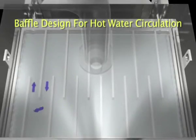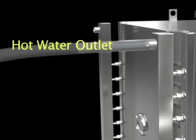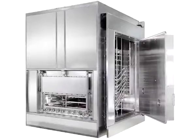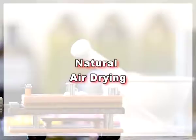It is usually employed in a closed circuit and allows a proportion of latent heat to be recovered by recompression, a feature which is not possible with conventional air drying. So, in this process, the latent heat of drying is used for drying the product. The process has potential for use in foods. It is carried out at reduced pressure to lower the boiling point.